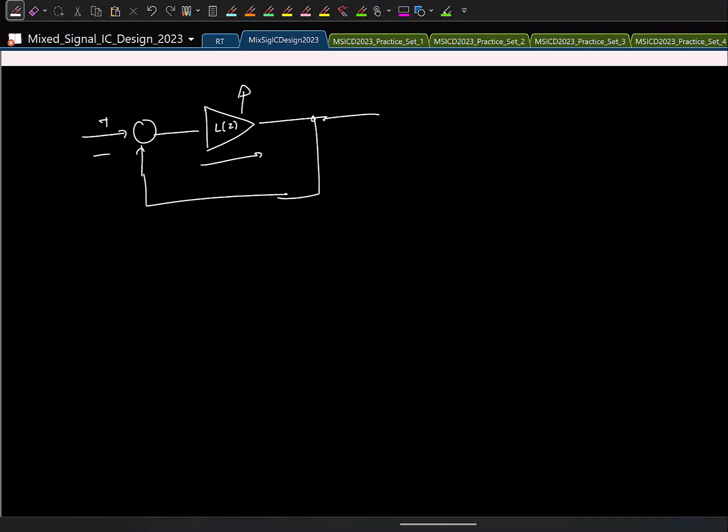First answer is correct. If we keep increasing the order, we'll have more and more delay. Simply because if you think of it in continuous time, first order will require one RC, loosely speaking. Second order will need one more set. So we'll have more capacitors, more delay. And if you have a lot of delay in a negative feedback loop, what can happen? It can become unstable.